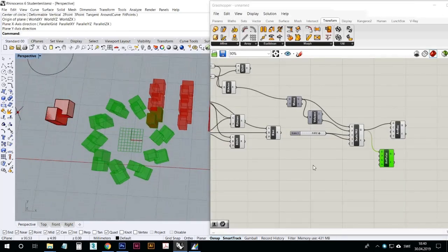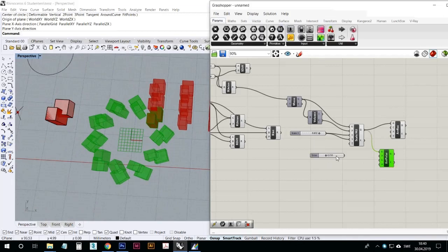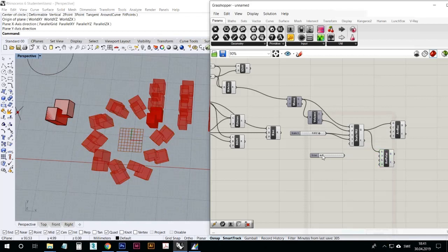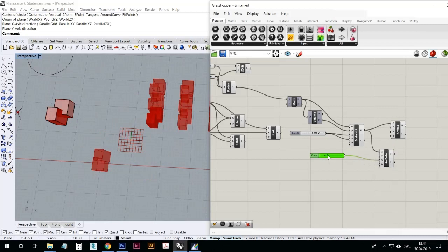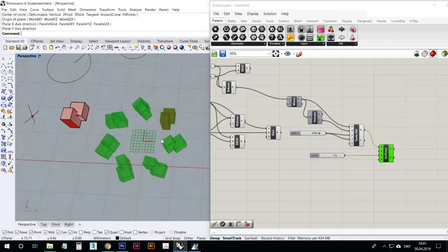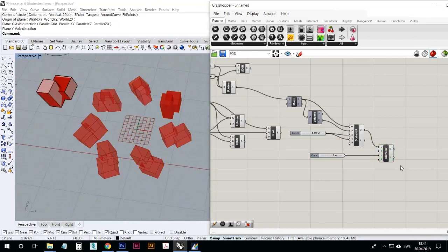And you can then actually set a slider here in the middle, maybe from 1 to 10, with an integer, of course, because it only works with integers. 0 will make it not work, and then you can put it into n here and simply multiply them around the center point like this. These are the things you can do here. Maybe one can apply it to something else in exactly this shape, but who knows what you can need it for. Yes, so that's the polar array transformations.